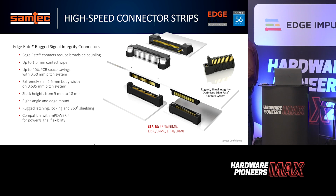So in here we see mezzanine type connectors. Again, the message here is you have multiple options that will fit different applications and different requirements. So if you want something that is really robust, maybe we can recommend you other connectors than if you're looking for really good signal integrity. Normally, again, edge rate series, where we use the edge rate contact, is the sweet spot for most applications in 0.8, 0.635, and 0.5 millimeter pitch, different stacking heights.